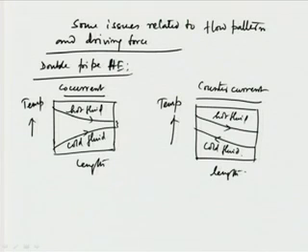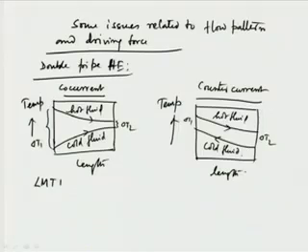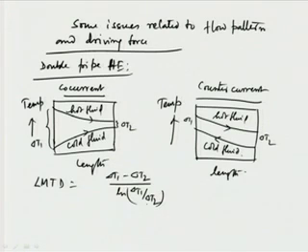Fine. Now the question is that we can also find out the LMTD, because we have seen that in both the cases delta T gradually changes along the length. So here it is delta T1 and this is delta T2. In this case this is delta T1 and this is delta T2, as they are gradually changing. We have seen already that for parallel flow and counter flow, the driving force is given by the LMTD, the log mean temperature difference, which is delta T1 minus delta T2 by ln delta T1 by delta T2. So this is the driving force.